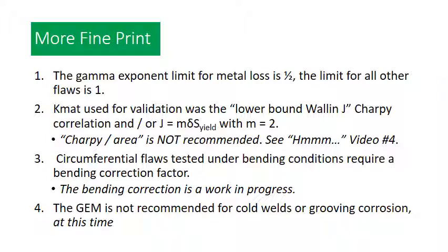The Charpy over area is not recommended. If you see one of my previous videos, Pipeline Integrity, Things That Make Me Go, video number 4, I demonstrate that I believe that Charpy over area correlation was done under plane stress conditions, which is not, strictly speaking, correct for plane strain conditions that we're looking at in this video.